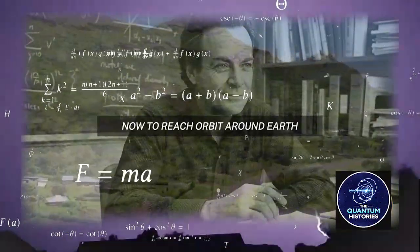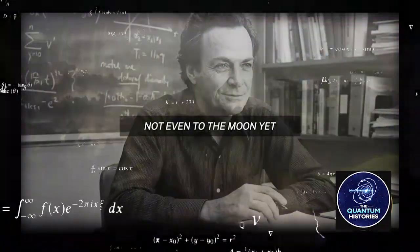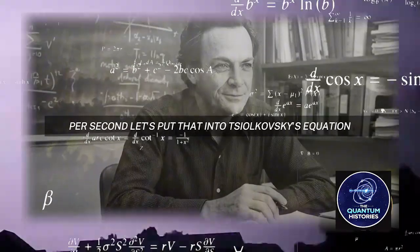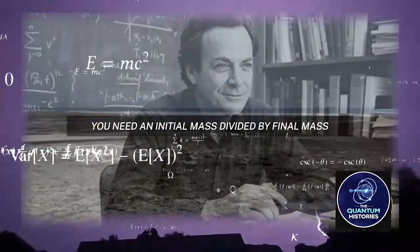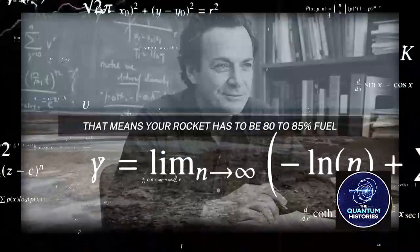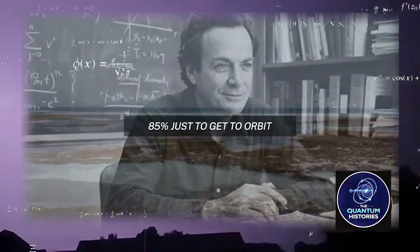Now, to reach orbit around Earth, just to get to low Earth orbit, not even to the moon yet, you need a velocity change of about 9.4 kilometers per second. Let's put that into Tsiolkovsky's equation. What mass ratio do you need? You need an initial mass divided by final mass of about 5 or 6. That means your rocket has to be 80 to 85% fuel. 85%, just to get to orbit.